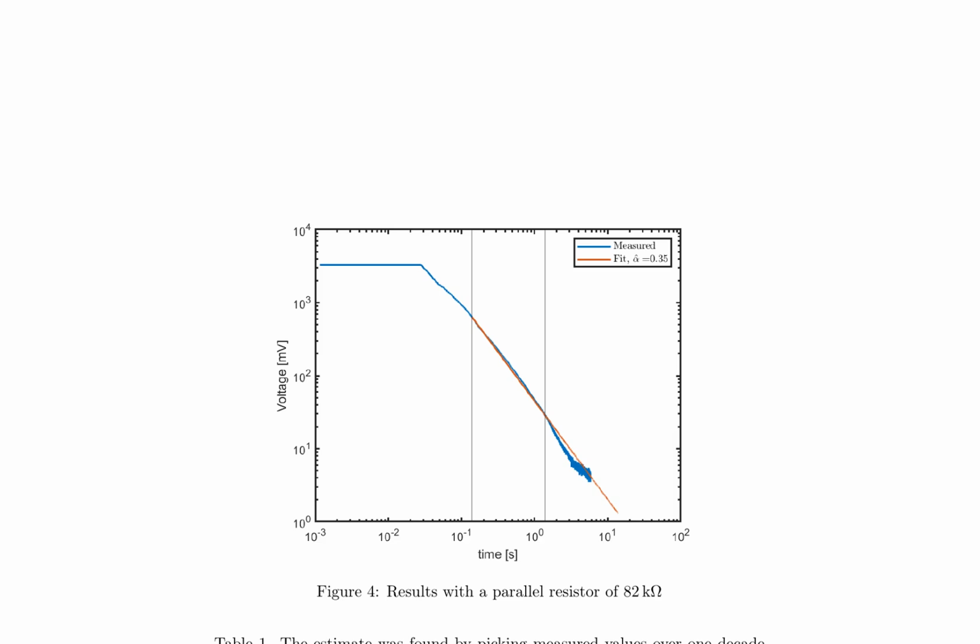The figures also demonstrate that the relaxation follows a power law for about 2 decades of time, confirming the validity of the two-term time domain multiplication definition of current in a capacitor. This is in contrast to the constant phase element, which when interpreted as a time and frequency varying capacitance, follows the time domain convolution of equation 6.